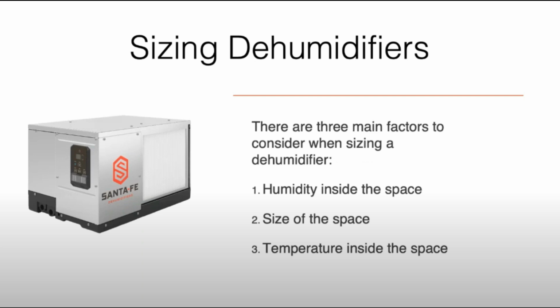Now, if you have a dehumidifier that can't handle the moisture load in that space, it's going to run and run and run because it can't achieve that RH setting. This can make their utility bill go through the roof. This is why you always want more capacity than you need. The last thing you want is a homeowner calling you because you installed a dehumidifier that isn't doing what you said it would do.